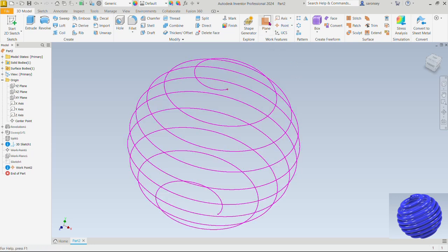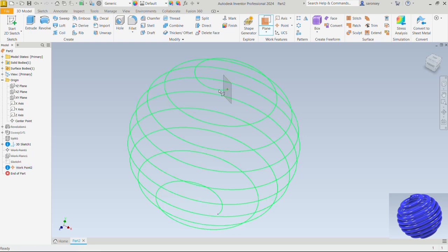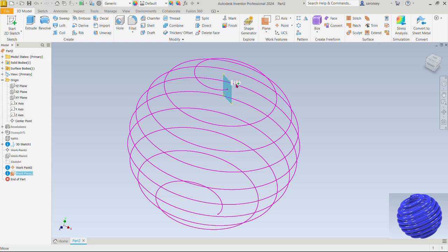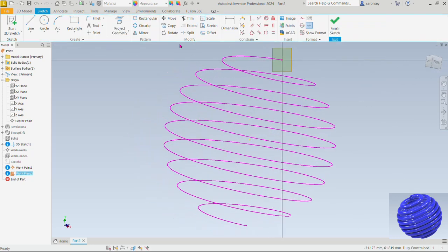Now let's draw again the profile to sweep, and so let's put the point right here. Awesome. Now the plane at that point, and then we will touch this line. Now let's select that plane, and we would create our sketch. Let's draw the circle from that point. But before, let me project this point onto the plane. Pick the circle command and draw the circle of diameter 20, and enter that.